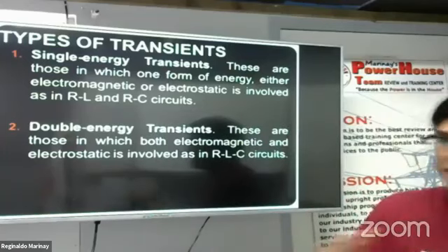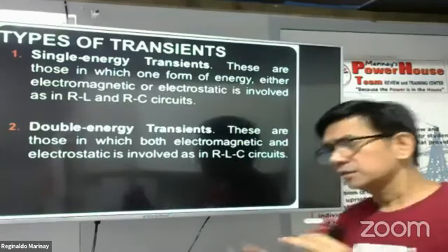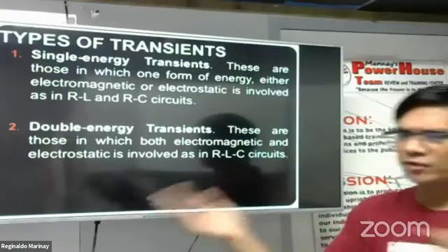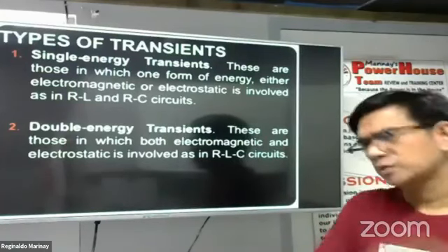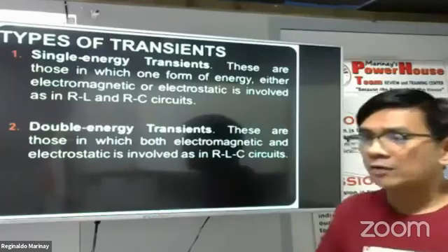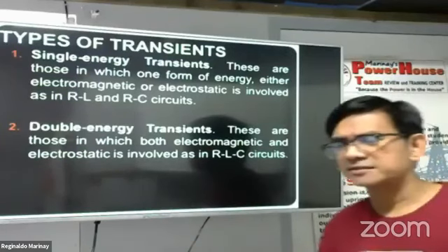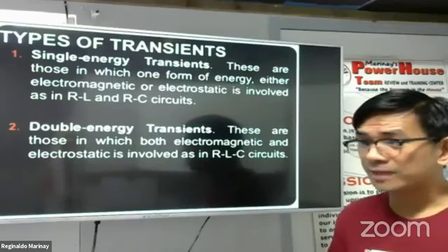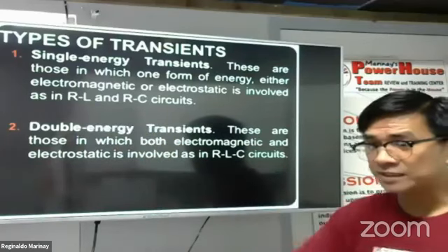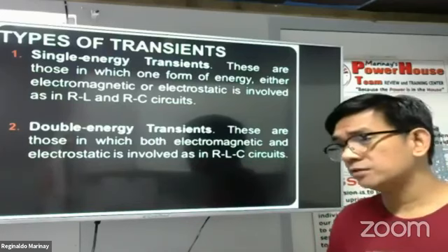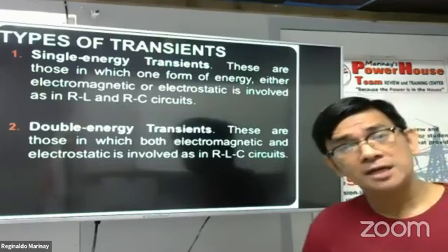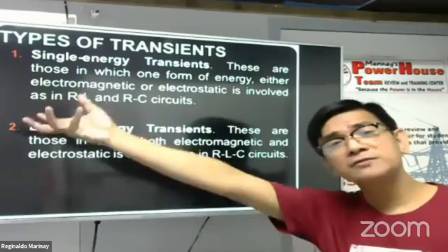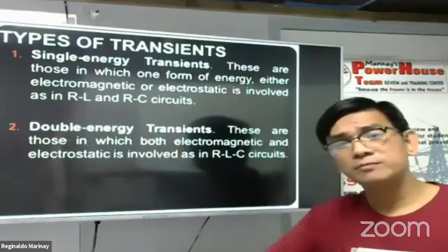They oppose each other. We will study this in power factor correction. You have so many motors, your power factor goes down. What is the effect? You draw a large amount of power or kVA from the source. And also you are drawing a large amount of current from the source if you have so many inductive loads.